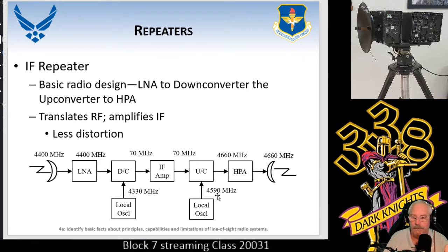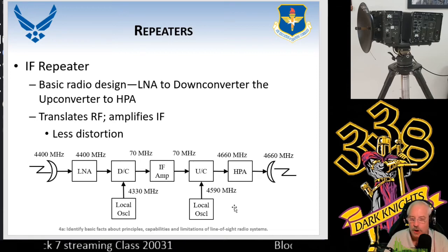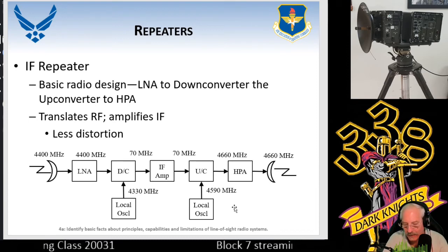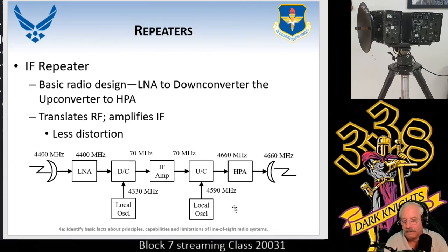Are those local oscillators? They're not fixed, are they? Normally they are, unless you change the frequency receive and transmit. When I say fixed, I mean there's no way to get in there and manually change them. So to answer your question, when you flip the thumb wheels on your front panel, you're actually changing the oscillator. That's the only way that you can change it. If you're looking at whether it varies or anything like that, it shouldn't.